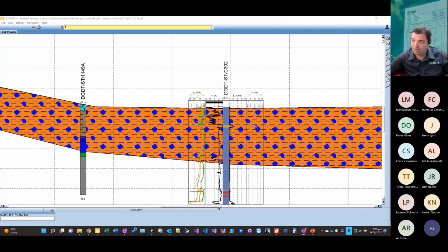I think Amir said, should we derive soil layers manually? Well, I guess that's what I did. But you can have surfaces in the database and present the surfaces like as lines, right, on the cross section. So gINT doesn't automatically join up lines into that, not totally automatically. You have to model a surface and then present it.